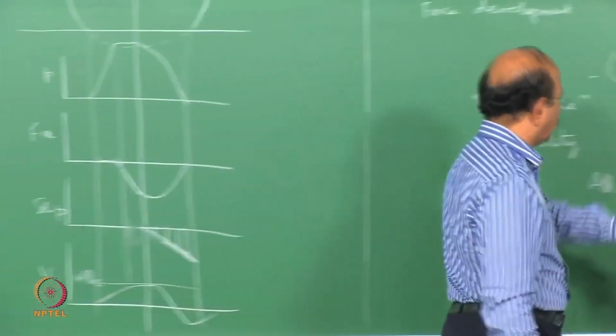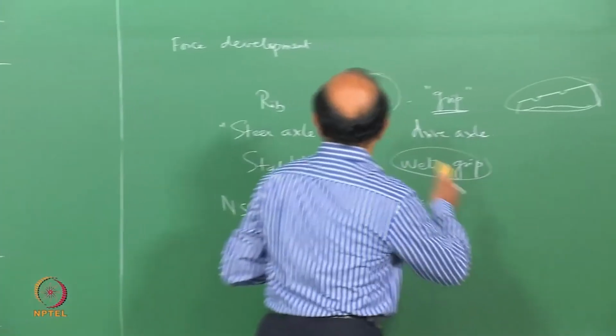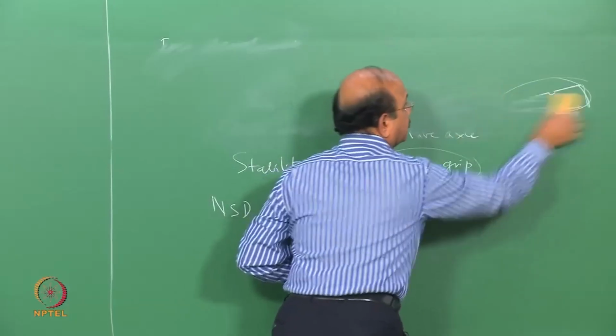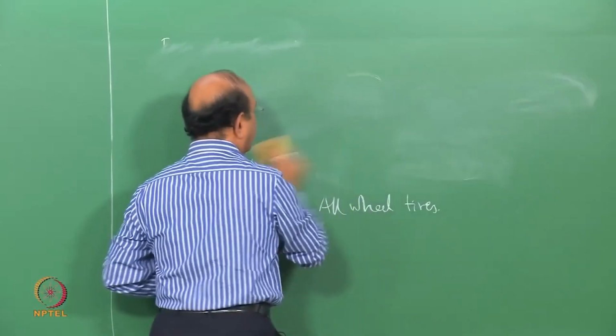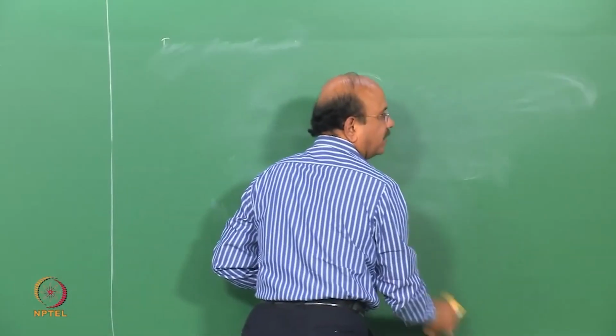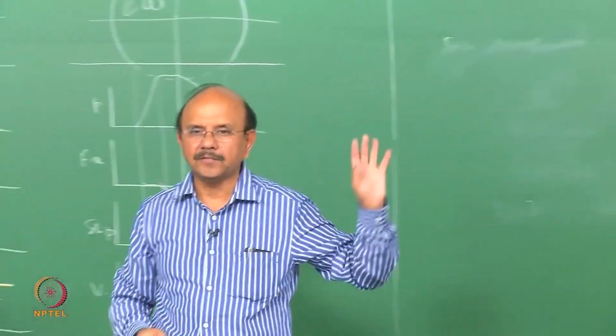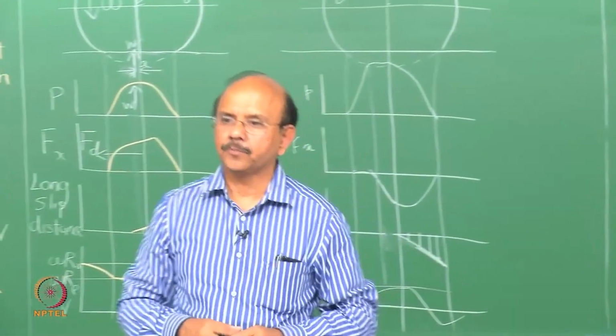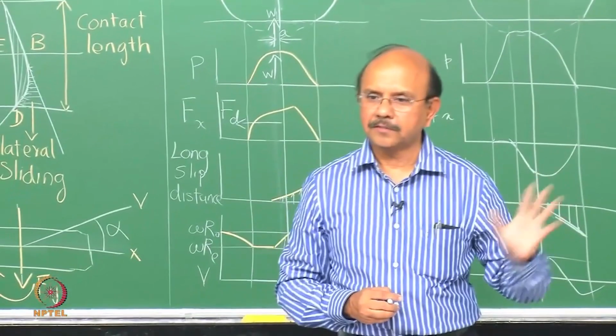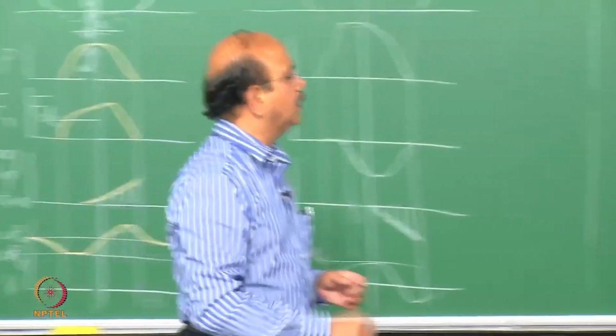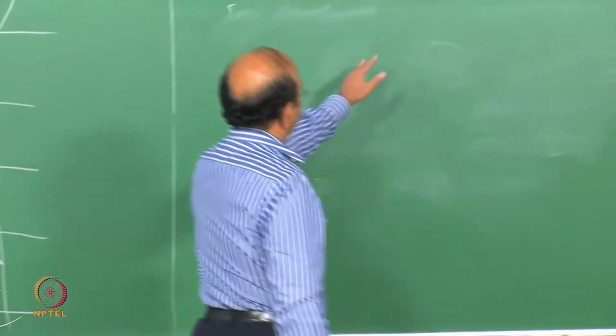There's a lot more to that question, and anyway, a quick answer to that question is this. The contact pressure distribution, as I said, is local bending. Instead of understanding all these niceties inside local bending, it is better to look at contact pressure distribution from a finite element analysis, which you would understand quite well.